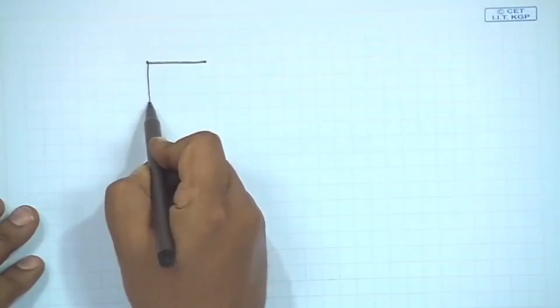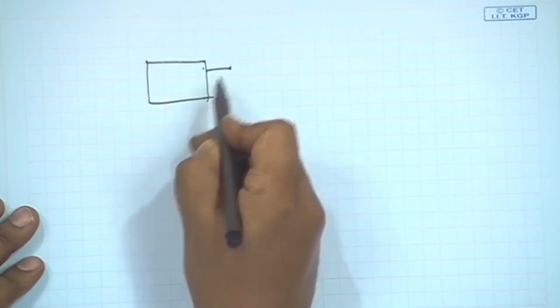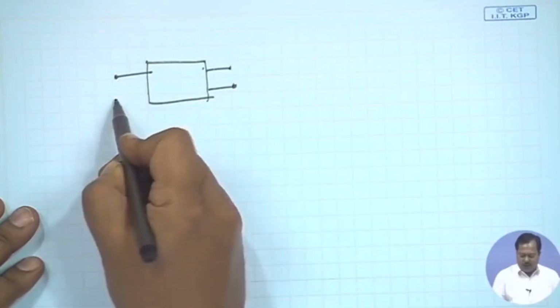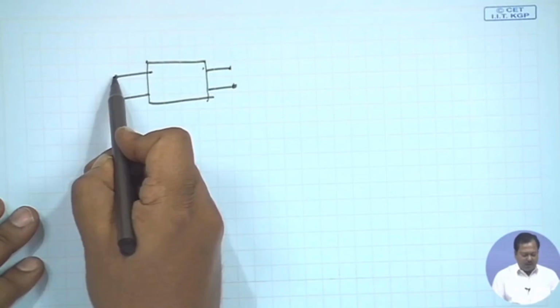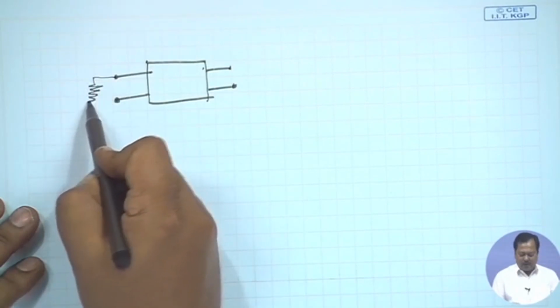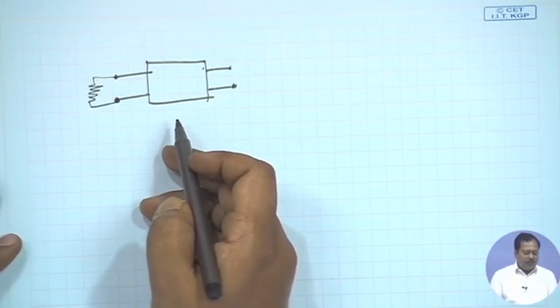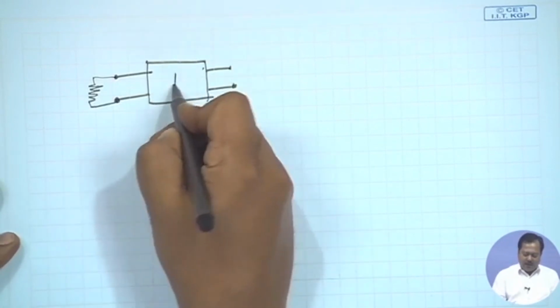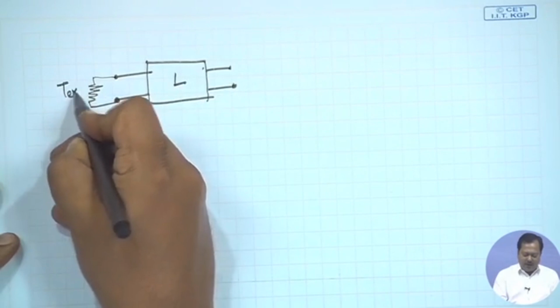So, now we are considering some external noise which is incident from the left hand side, and altogether we want to express this system by some equivalent noise temperature. Then how to calculate it? So, we have a two port network which is providing some internal noise, and it is also connected to some external source of noise which can be given by T external.